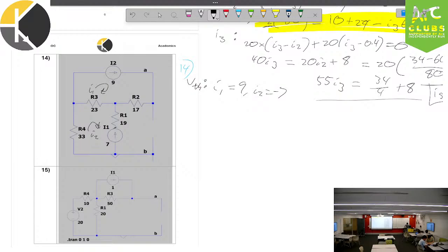Now, how do I get from B to A and measure voltages? I need to track it around somehow. The way that I'm going to go is along this here resistor path. Okay, so I'm going to run up this resistor, across this resistor, and across this resistor to get there. Okay, now, why am I choosing this route? I'm able to calculate voltages over resistors very easily. I cannot do so for current sources, right? And so, plus minus, plus minus, plus minus.